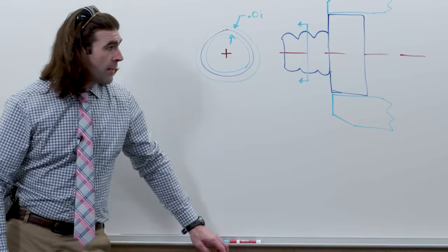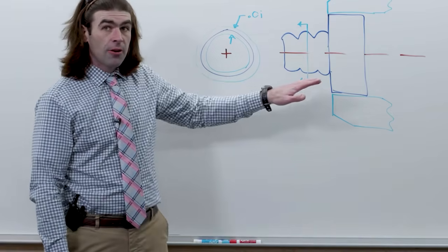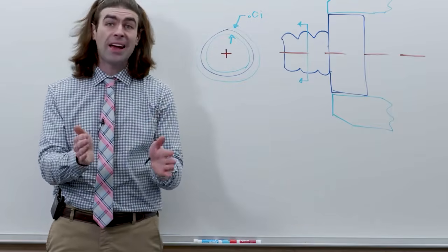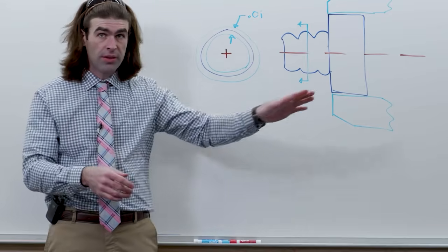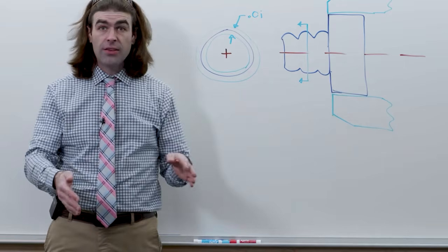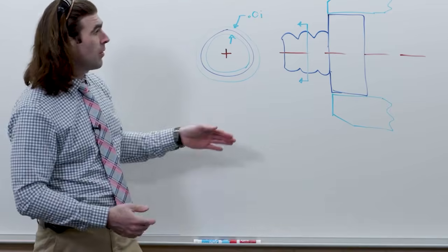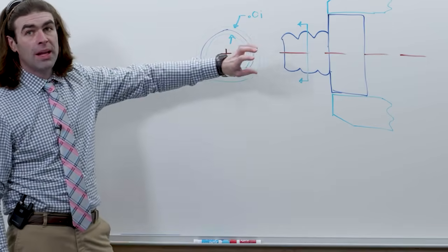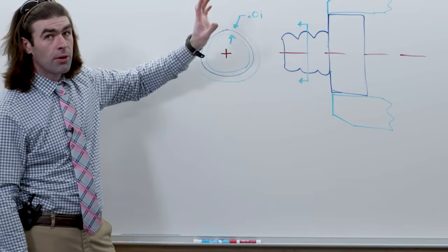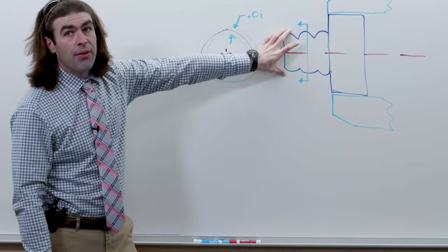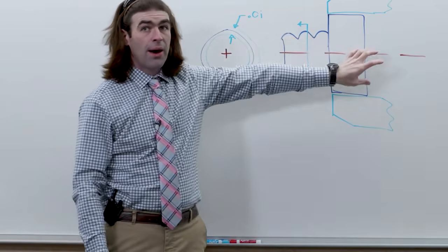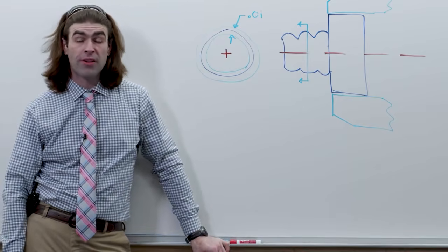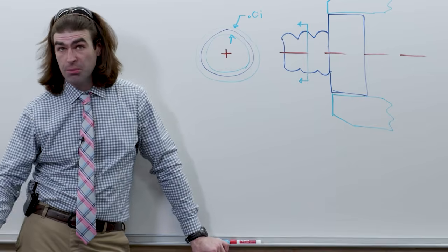Now, I've tried to draw the jaws of a chuck here. When you clamp onto the datum feature, the axis of your inspection equipment, so in this case, a chuck, is the axis of your feature, right? So whatever the axis of this is, projects through here, that's what you're spinning about, okay? So it's important to realize you're not spinning about the feature you're measuring, you're spinning about the actual datum. So in theory, that should be the most important feature where it mates up at assembly.